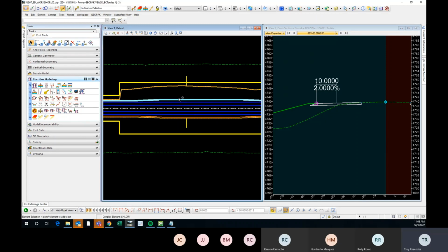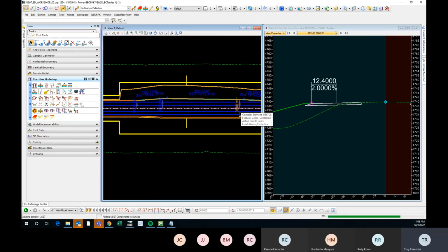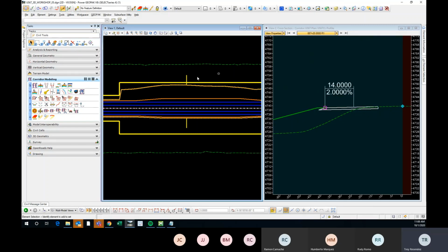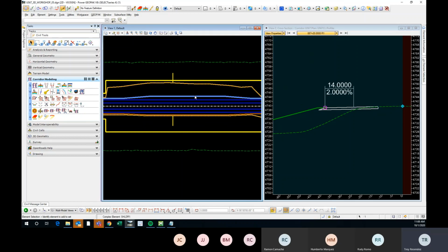And what's even more cool is you can update these values and the model will update as soon as you change the values. So it's pretty nice, and you can have a lot of control in your model if you know how to use point controls and parametric constraints correctly.